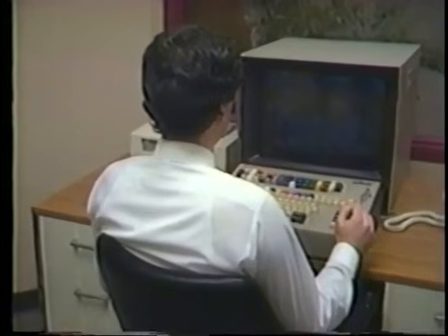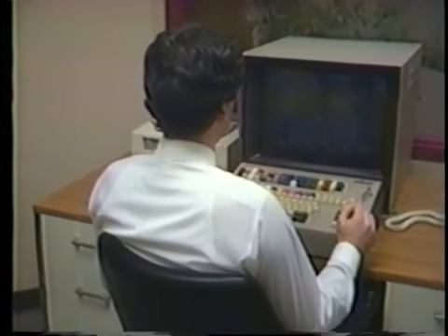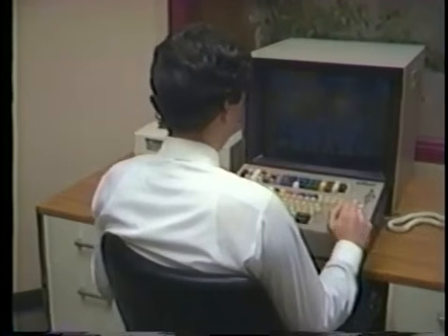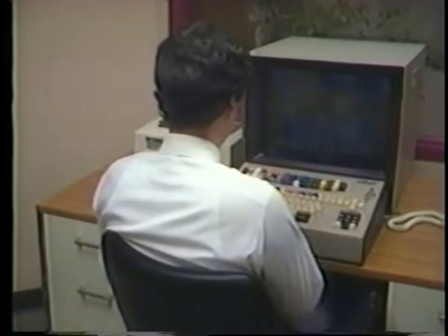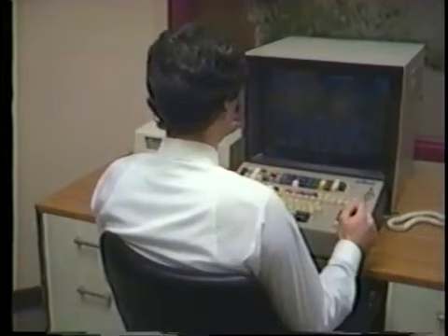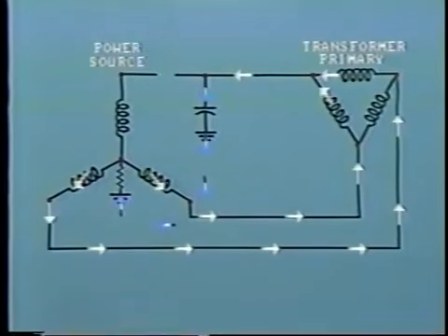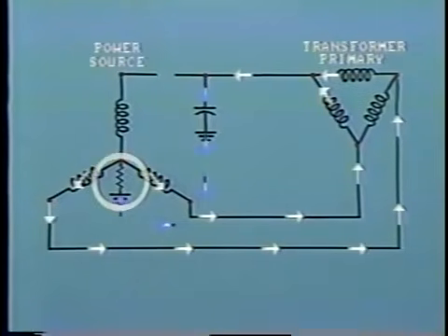Clearly, in designing the power system, the engineer tries to ensure that specific values of impedance and capacitance will not lead to resonant conditions. Incidentally, you may have already perceived that one way of reducing the resonance effect would be to insert a resistance in the neutral of the source transformer. But didn't we already point out that we prefer to have this neutral solidly grounded? This is yet another example of opposing interest and compromise that we often meet in power system design.